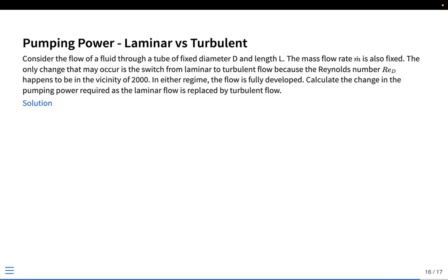And the last problem highlights one of the important fundamental problems in all these heat transfer calculations: you try to increase the heat transfer coefficients, but when you do that, you are doing it at the expense of pumping power. As we have seen, if you move from a laminar to a turbulent design, your heat transfer rate or heat transfer coefficient will all increase, but at the same time the corresponding values for the pressure drop or the skin friction coefficient will also increase. So both skin friction coefficient and Nusselt number will increase. Depending on your particular problem, if the cost of increasing the power consumption is lower compared to the benefits you are going to get from the increased heat transfer, then you would go ahead with that strategy. If it is otherwise, then you would have to come up with a new strategy.